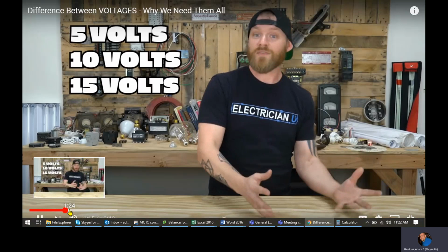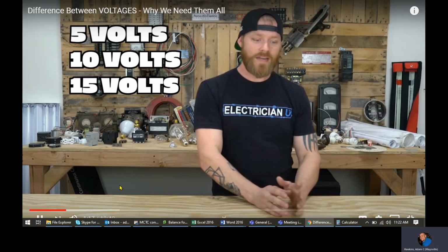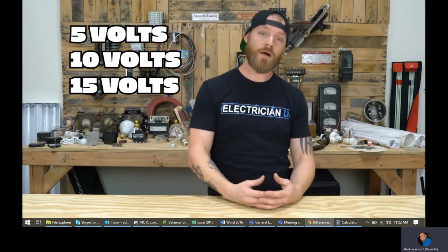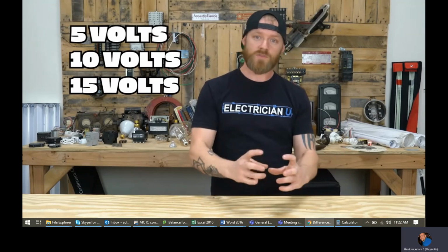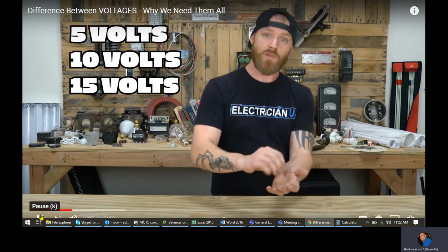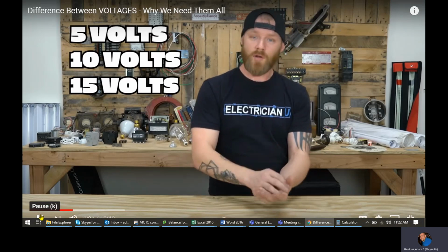You're going to come across probably 5 volts and 10 volts, maybe 15 volts DC. A lot of times in lighting control systems or energy management systems, if you're going to work in places where there's refrigeration and remote monitoring, a lot of those systems work off of communication signals back and forth, where they're sending a small little 5 volt DC pulse.